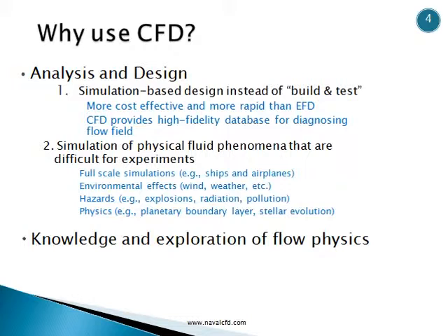Another point is that you cannot do a full-scale test, because one ship may be 300 meters, and you cannot test a 300-meter ship in a tank. So you have to reduce the scale, to a length of maybe 5 to 7 meters. Similarly, wind, weather, and many other conditions may affect your research.